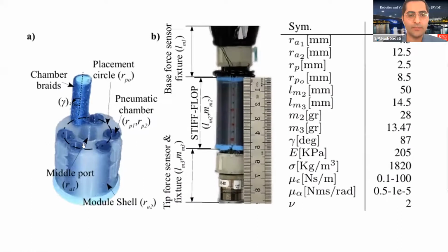Basically, it has an overall silicone body with internal ports: outer radius, inner radius of a cylinder, and 6 braided pneumatic actuators implemented with a small fixed offset from the center, and soft caps at both ends.